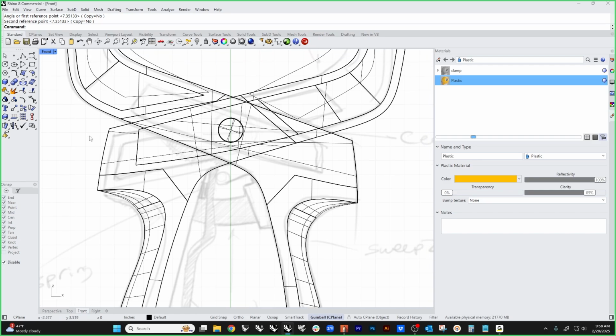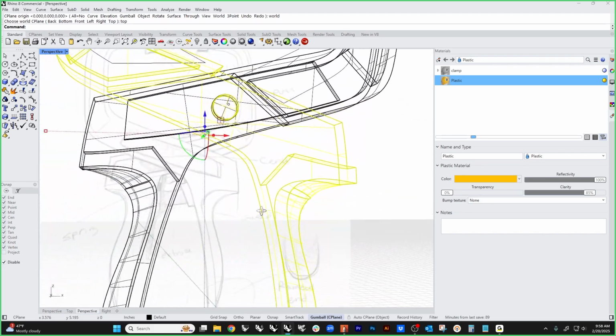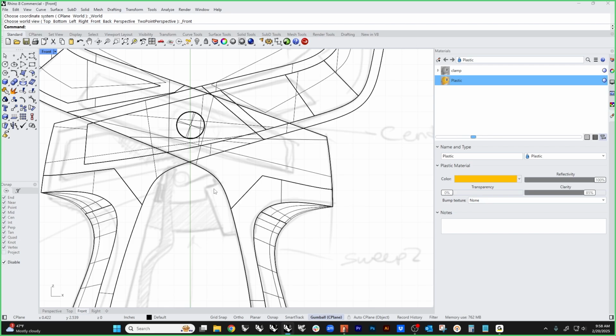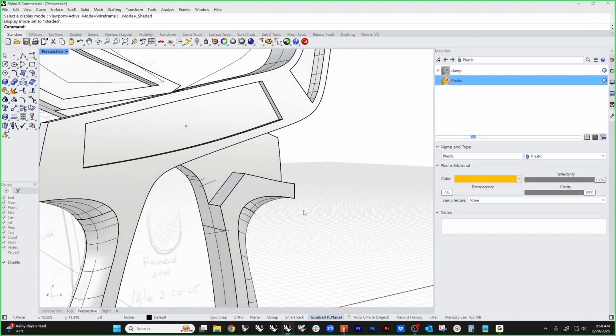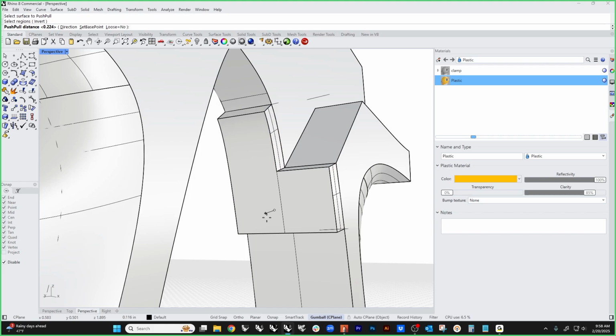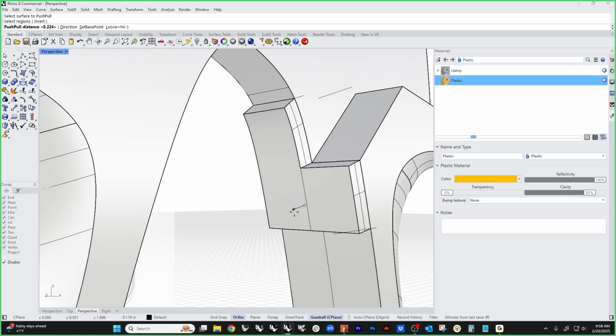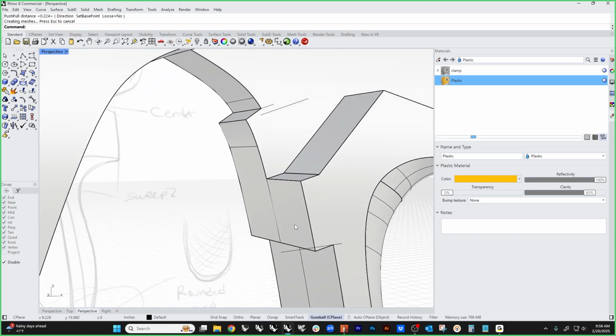And in this case, there's a little detail on the inside of this that fastens the metal part. So if I project a line there and a line there, that's going to put two lines on the surface that then are going to allow me to push-pull that little detail out. And in this case, I only need the back one, so I'm going to do that.